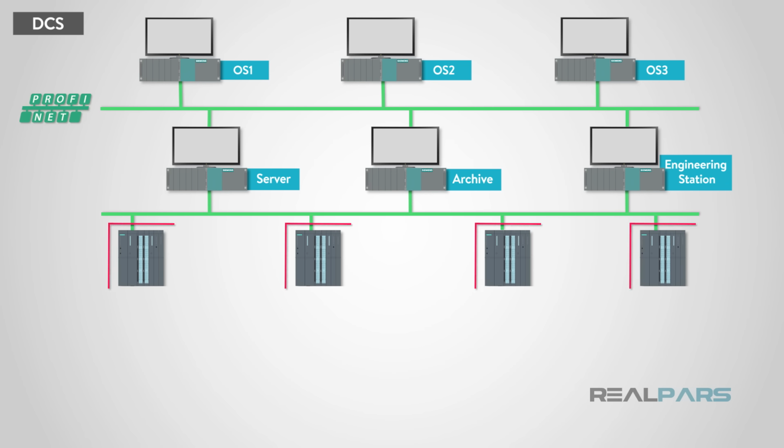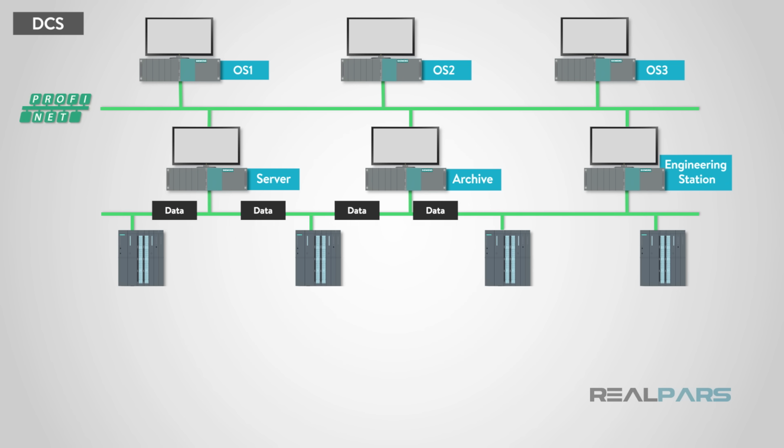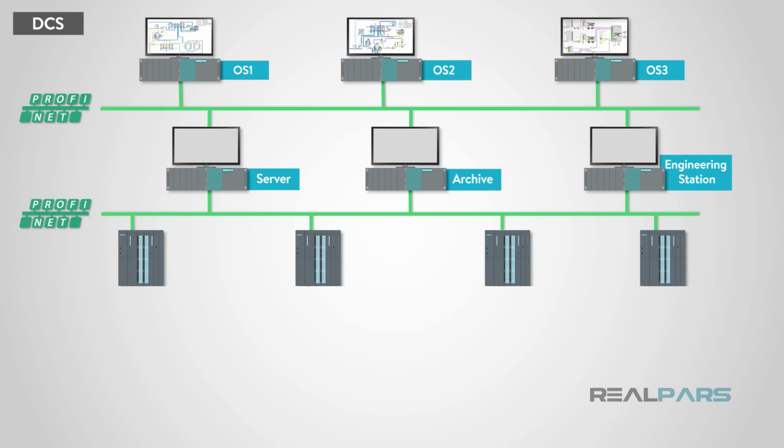At the next level, you have the master controllers that supervise the individual processors as well as I/O modules. These controllers are also responsible for providing the data to the servers, which in turn supply the data for the graphical interface. Industrial Ethernet is typically used for communication with the previous level. Fiber optic may be used here when Ethernet cabling runs would be too long.